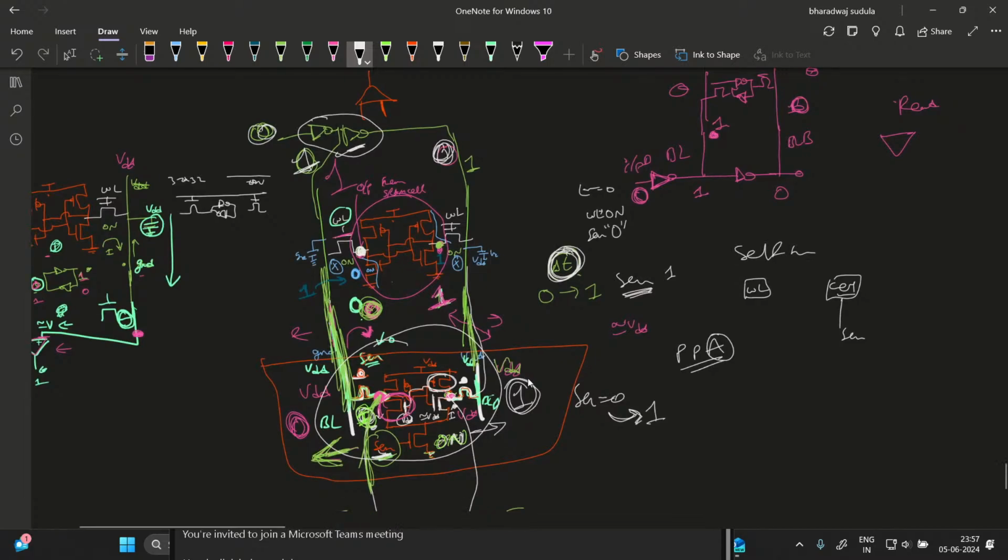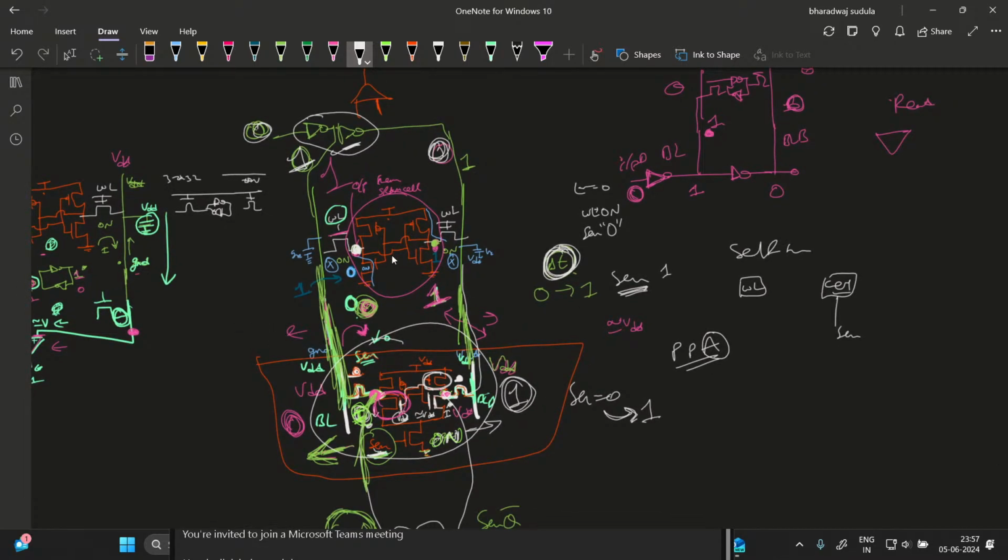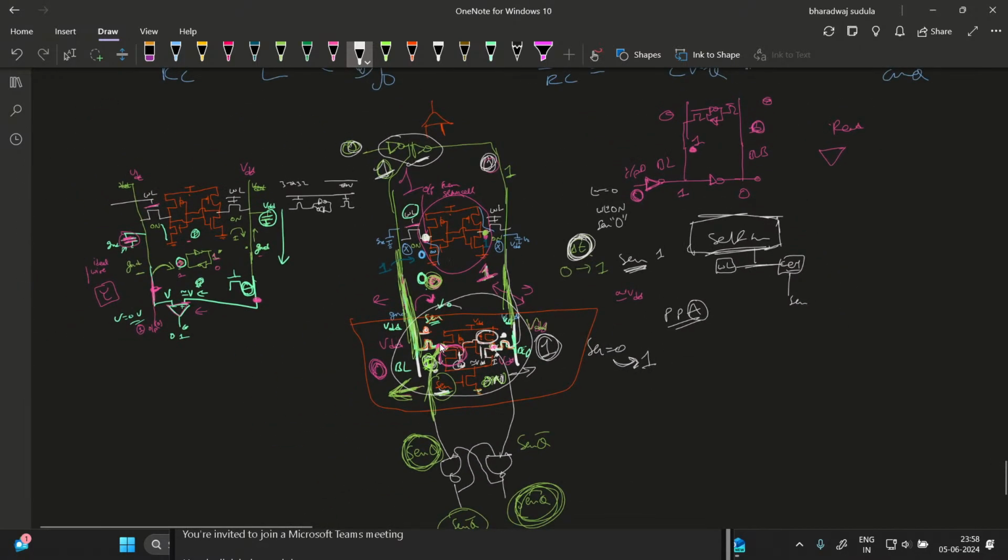For our project purpose, we could actually just demonstrate how the read operation occurs and write operation occurs. And self timing, if it is there, that would be nice. So you haven't tested the self timing right now. Actually, my self timing circuit is working, but I have to change this delay, word line delay and cell delay. They are not actually matching with the actual SRAM cell. Okay, so the design is done, but the delay needs to be adjusted a little.